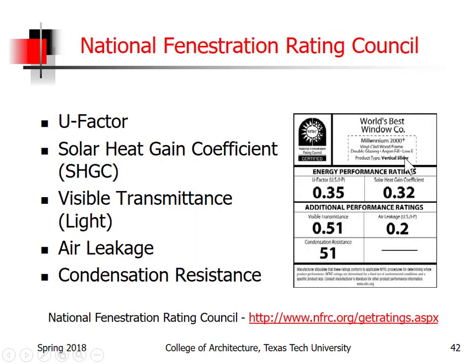I spoke about this. The National Fenestration Rating Council is the most common certifier of windows, but they're not the only ones. There are other people, UL. There are other people who certify them, and they certify all these things. The U factor right here, the solar heat gain coefficient, and you'll see visible transmittance.